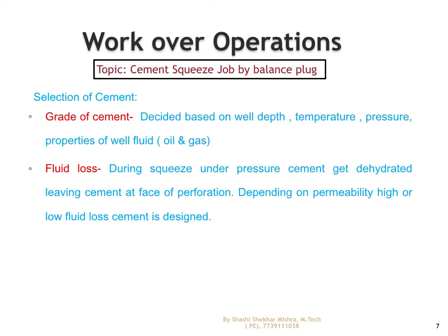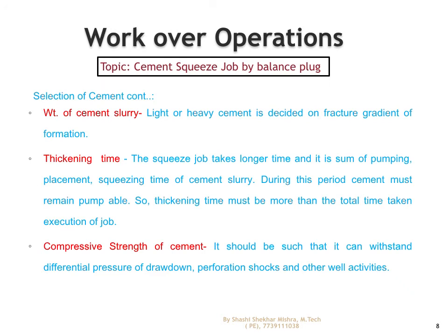Then comes the selection of the cement. Based on the previous data, we select the grade of the cement, fluid loss, the weight of the cement slurry, thickening time, and compressive strength of the cement.